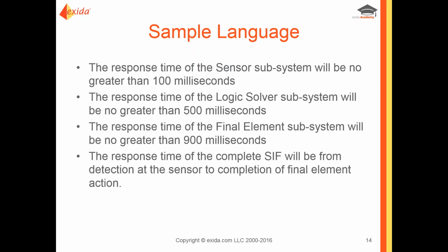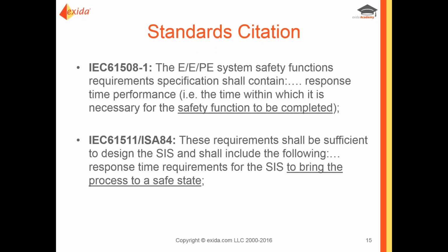There may be occasions when a function, in order to render a safe state within the time frame necessary, has to act much more quickly than maybe some of the individual components. So we want to make sure that the whole SIF is responding in a timeline that is appropriate. Even though we've defined design specifications for individual components, they don't necessarily sum up to the overall time.